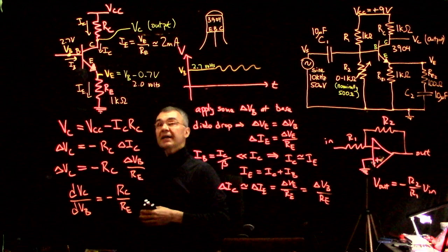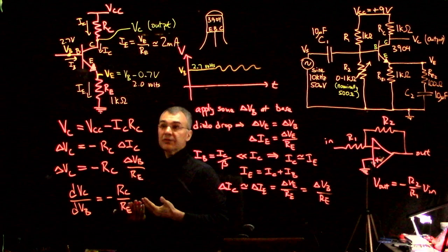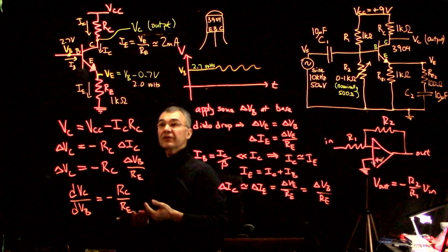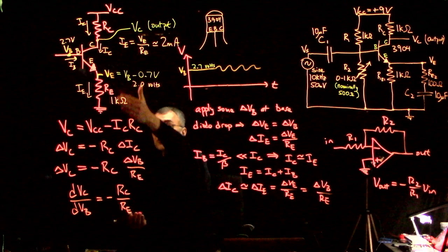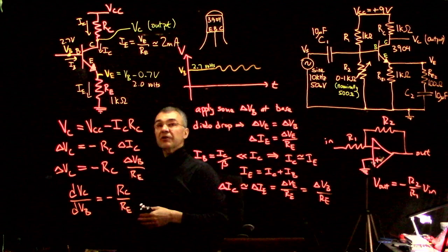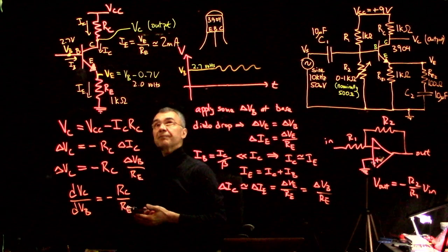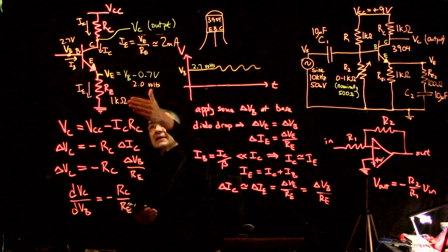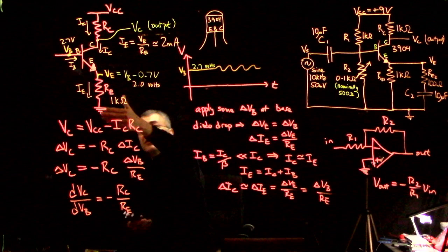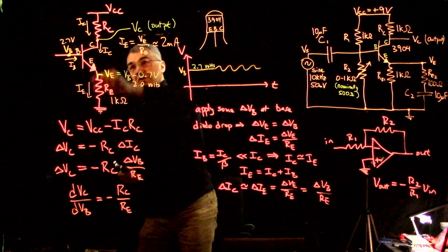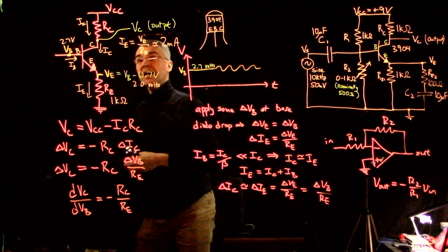And then because the transistor is active, not saturated, the same current that flows out the emitter flows into the collector, to maybe on the order of a 1% correction. So by changing the base, we're changing the emitter current, which changes the collector current.